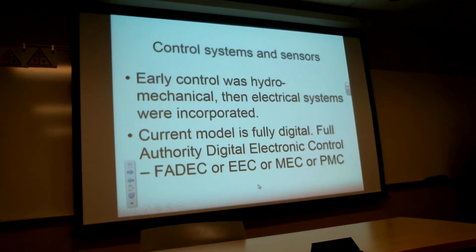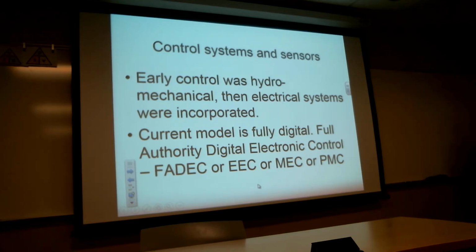Now again, the FADEC, there's really nothing for you to fool around with on a FADEC. They're sealed, and you're not supposed to be sticking your screwdrivers in those either. There are some connections to be made on them. There's plumbing and electrical to be connected to these FADEC. But there's really nothing else to do to them. When they don't work, what happens is there's a code comes up on the flight station. The code says, I'm not working. And then it's time to change it. What was the M stand for in the P? So which one? PMC. Power management control.